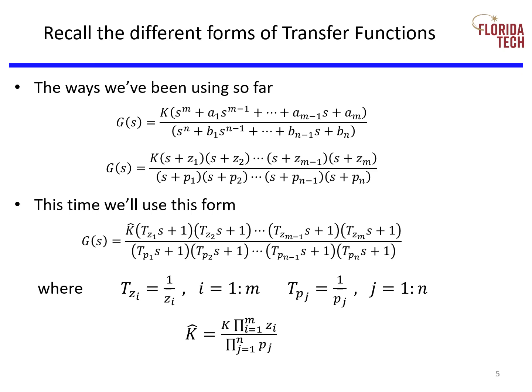So why go through all the pain of defining a new transfer function form? We'll soon see that to quantify steady-state error, we'll need to apply the final value theorem, which involves calculating limits as s goes to 0. This convenient form results in all the factors going to 1 as s goes to 0, leaving only the overall system gain of k hat. The one remaining item we haven't accounted for is a free s at the origin.